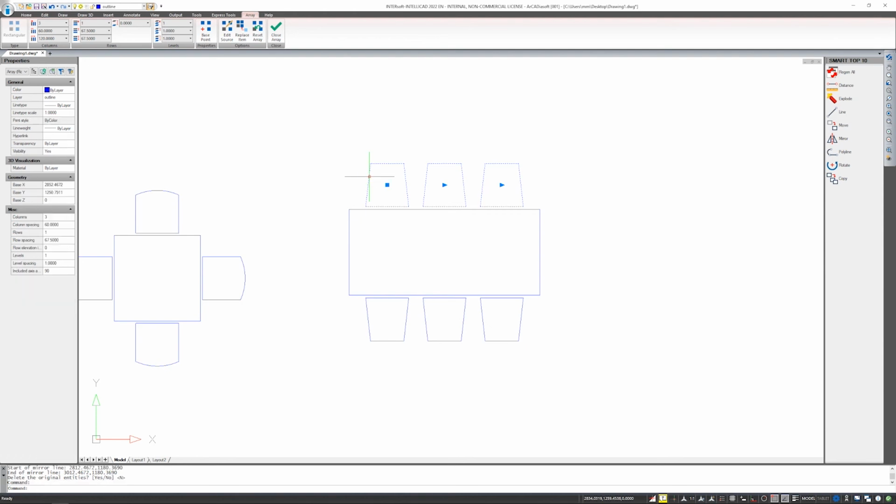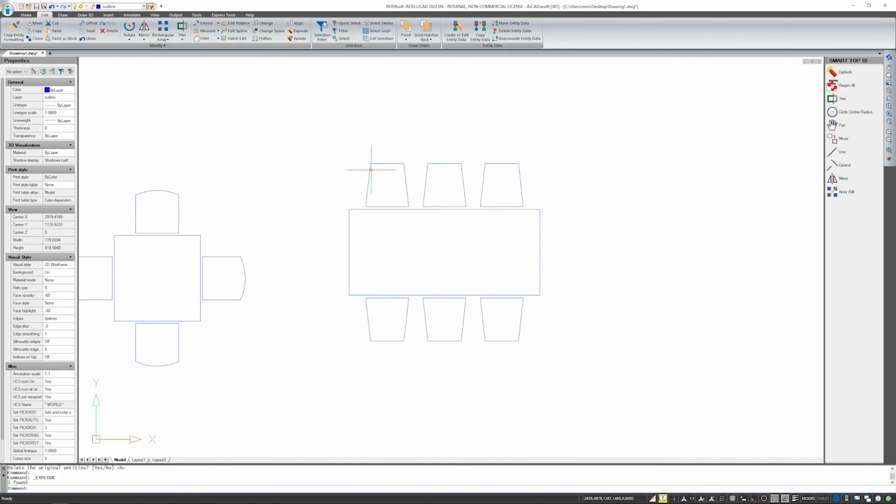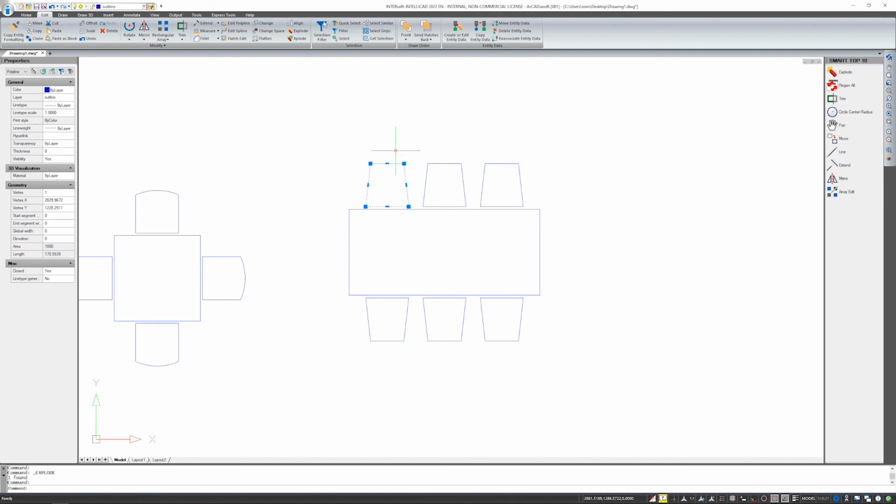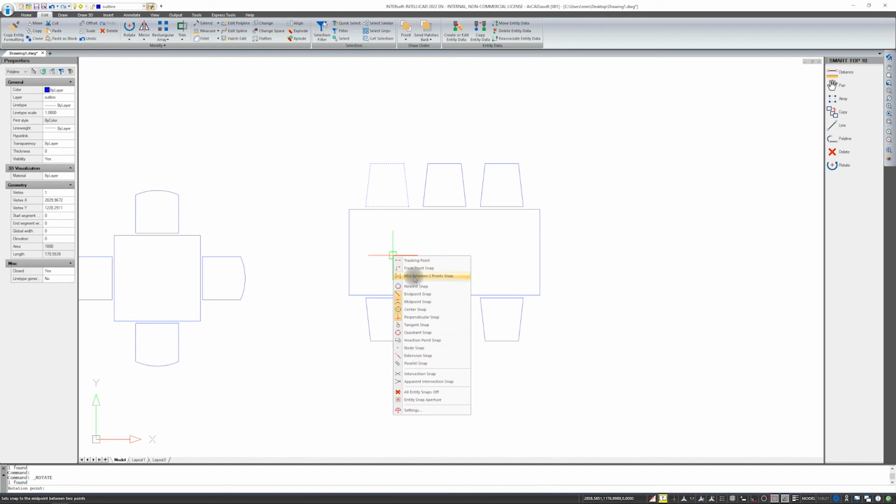Now, either with the option of rotating or arraying by 90 degrees, depending on what's convenient, you can draw 2 chairs. But first, you have to break apart the array. After you've done that, I choose the rotate option because at the same time, I will show you the option Shift and the right mouse button, which is pulling out the list of snap points.